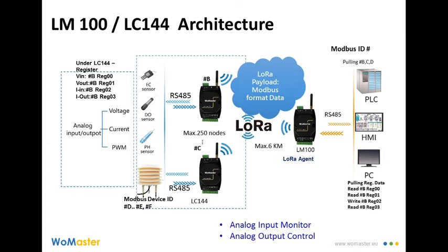LC144 can access the data from different sensors by the AIO, like pH value, temperature, PM 2.5, or else. We also have the outdoor environment sensor ES series for your selection. With the Modbus RTU, LC144 will transmit the data to the LM100 by LoRa.